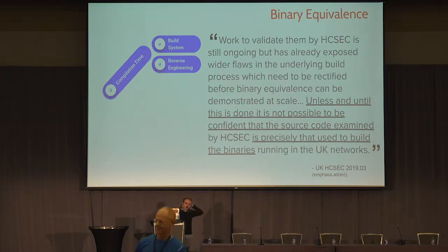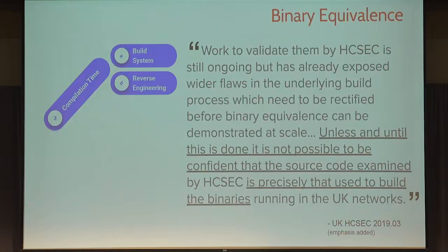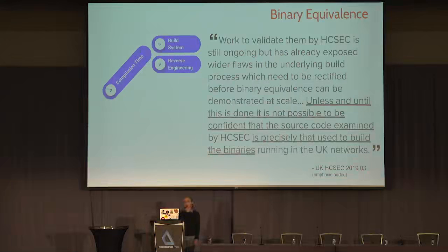So how do you check that the software isn't abusing or using a misprint or an incorrectness in that board? And so, you can check your code at compile time, look at the build system, reverse engineer the firmware that you pull from the board, which is what we did with Supermicro.